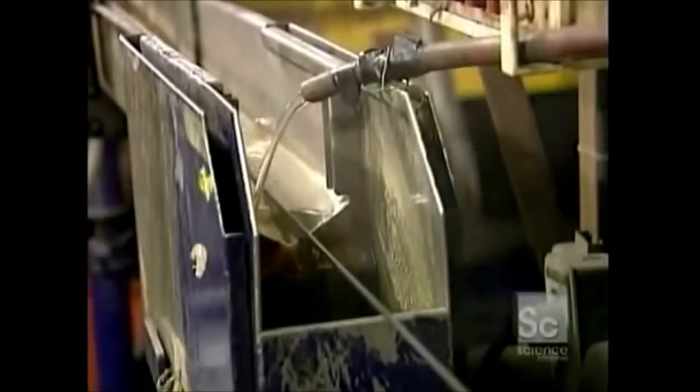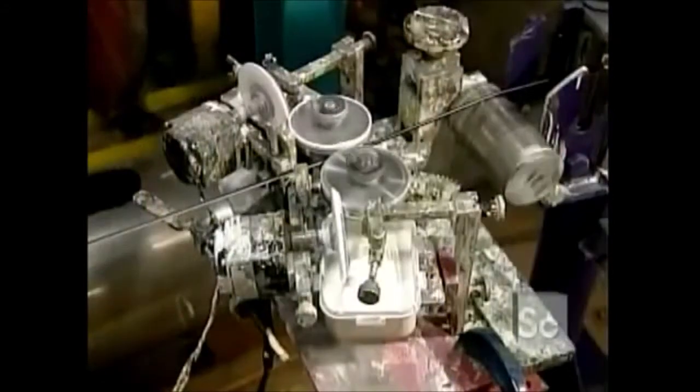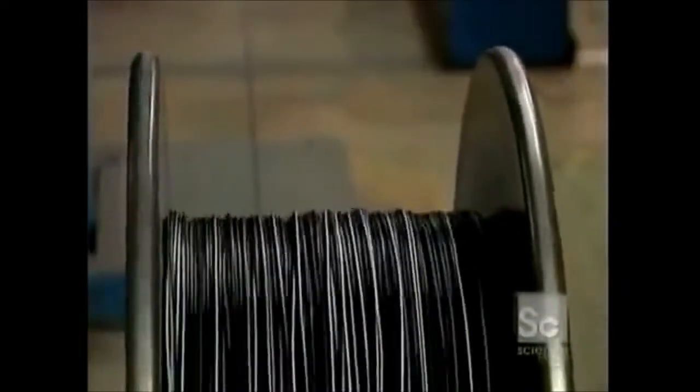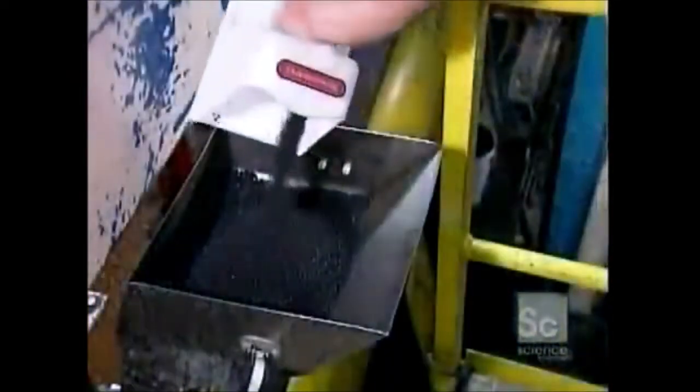As the conductor exits the machine with its new insulation, a precision laser gauges the diameter to make sure the insulation is uniform and the right dimension. The extrusion process has heated up the conductor, so it has to be cooled down with water. Sometimes 2 or more conductors are twisted together. When that's the case, a printing machine applies a white stripe to identify which is which. The client who's ordered the conductor specifies the colors of insulation. It chooses them based on how it wants to color code its electrical wiring.